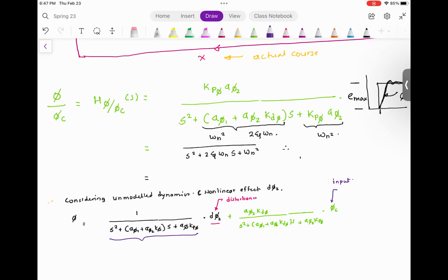If you turn it on very soon, then what will happen is your error will continue to get integrated. What it means is the controller effort from the integrator would continuously increase, and that would lead to something called integral wind up. Wind up means completing the full circle, going back. So that is the meaning of wind up. So once again, if you turn on your Ki integrator term when the error is huge, that huge error will continue to get integrated with respect to time.